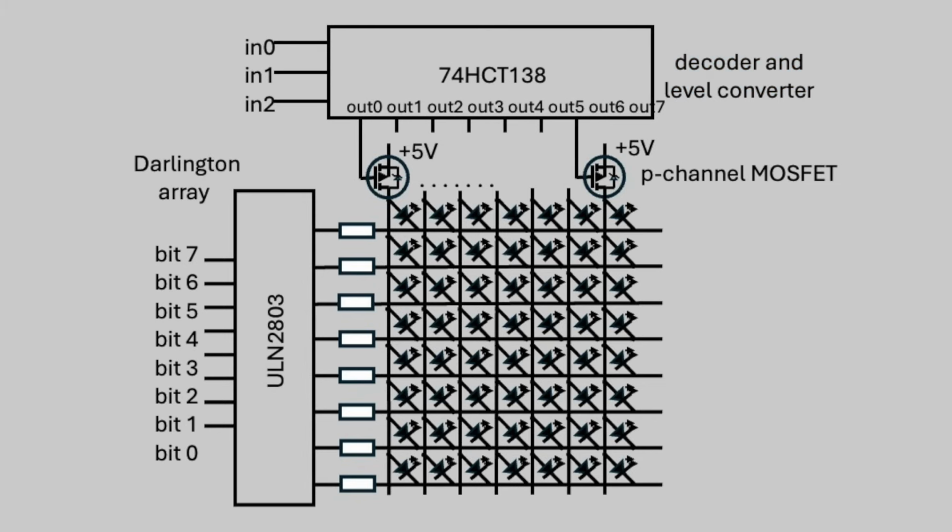As already mentioned several times, the display uses a multiplex process to control the LEDs. This has the advantage that relatively few components are required. At the same time, however, the process presents a number of interesting engineering challenges. As the picture shows, the 56 LEDs are arranged in a matrix with 8 rows and 7 columns. The microcontroller selects the columns in quick succession and controls the rows accordingly. If this sequence is fast enough, the eye perceives a static image of all LEDs simultaneously.